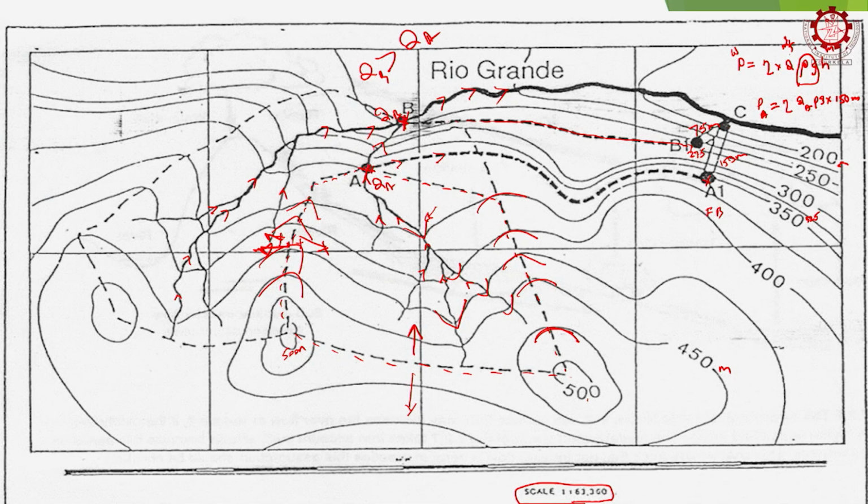So, once you mark the catchment area, if you know the rainfall in this area, say annual average rainfall is 1000 millimeters, then you know annually how much water is coming into your catchment area. Suppose your catchment area is found to be 20 square kilometers and the rain is 1000 millimeters, so 1 meter.